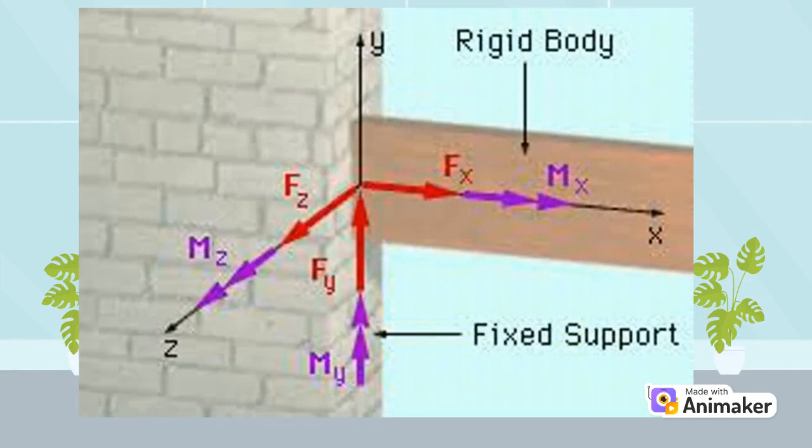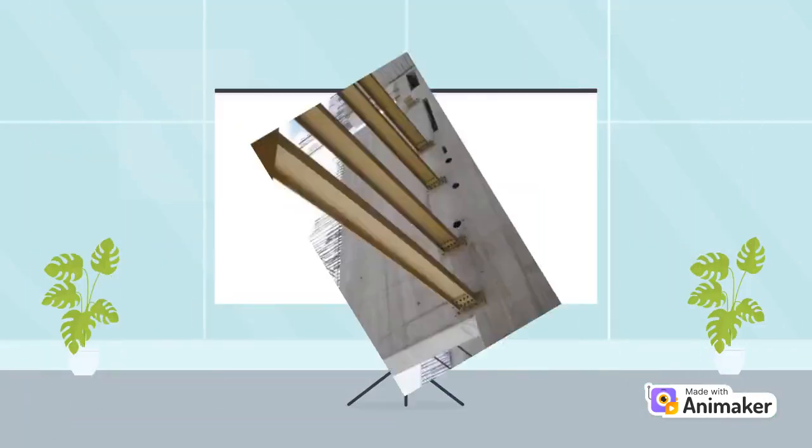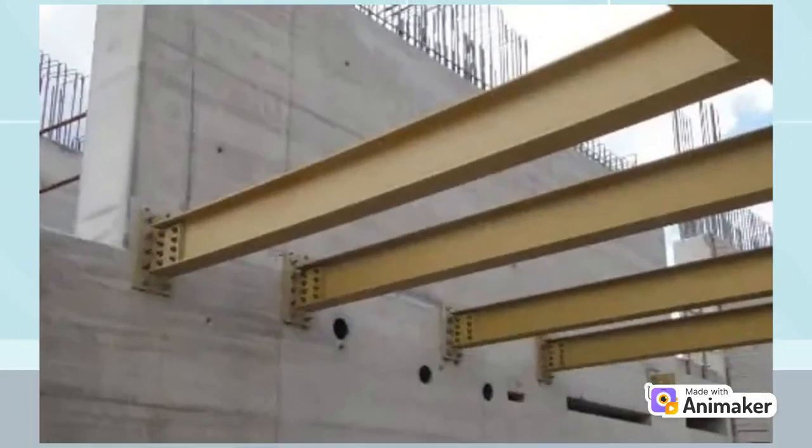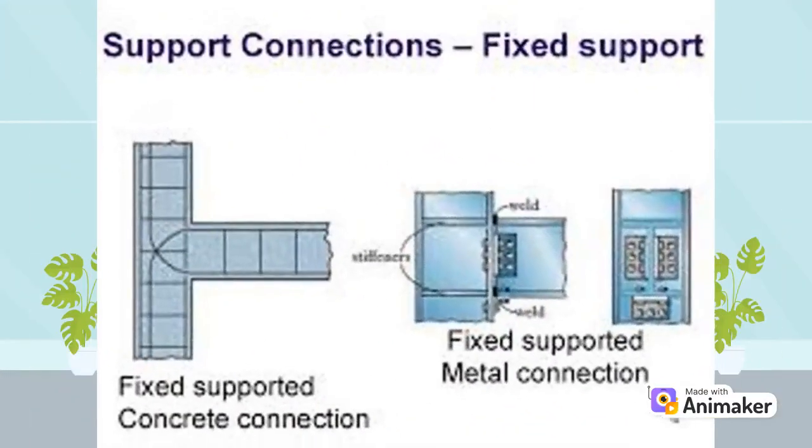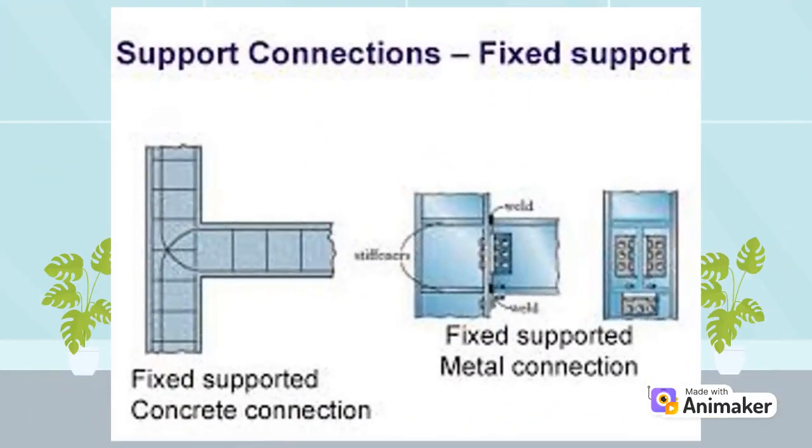A beam fixed in a wall is a good example for fixed support. Fixed supports maintain the angular relationship between the joined elements and provide both force and moment resistance. It exerts forces acting in any direction and prevents all translational movements, horizontal and vertical, as well as all rotational movements of a member. These supports' reaction forces are horizontal and vertical components of a linear resultant, and a moment. It is a rigid type of support or connection.